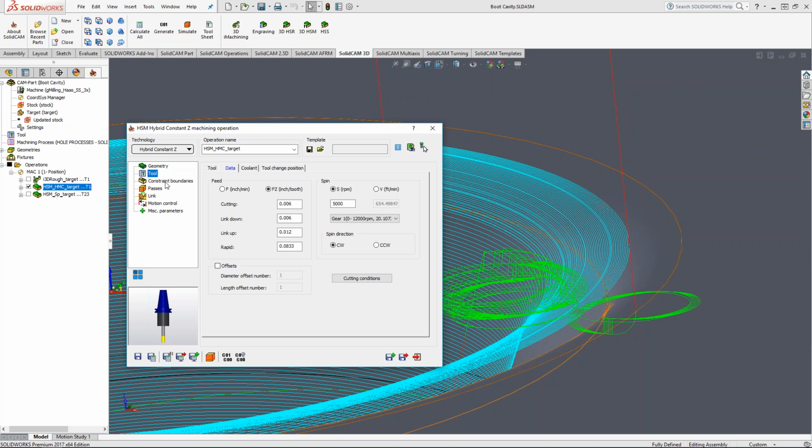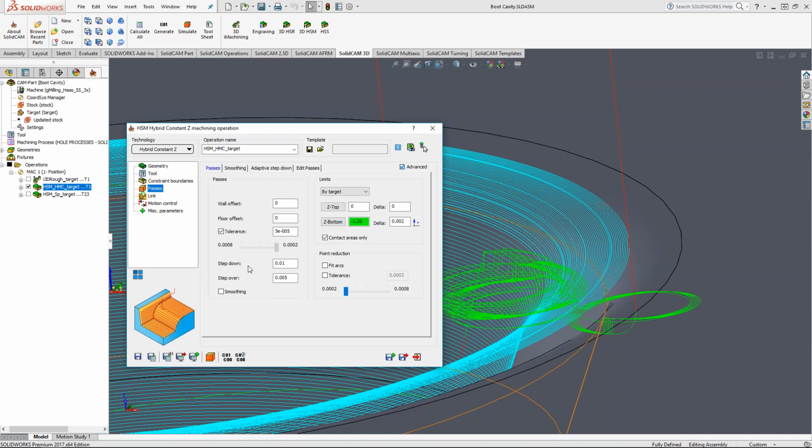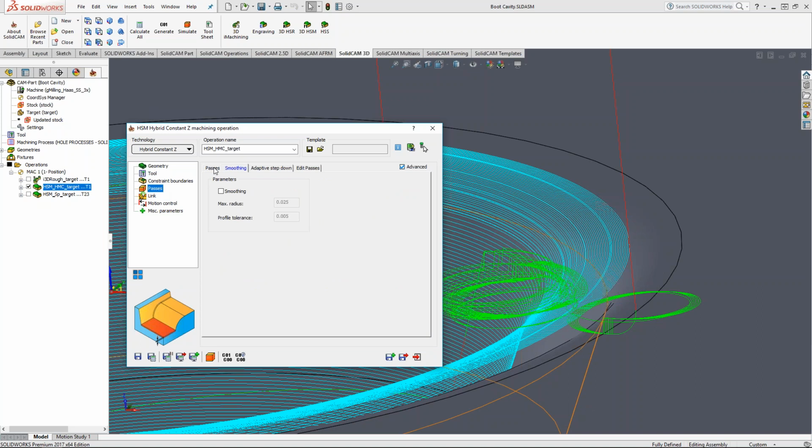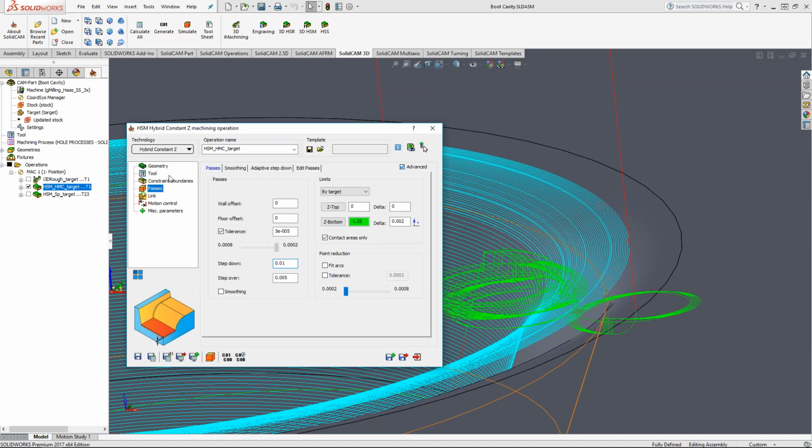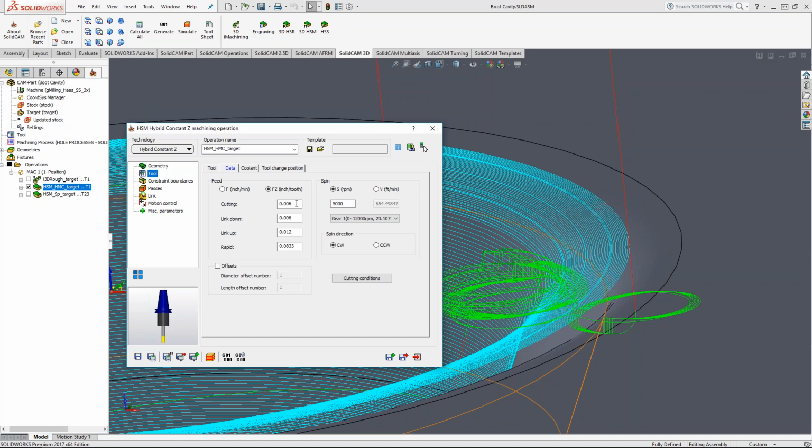So I think cutting this tool, the cusp height down these steps came out somewhere in the neighborhood of about 50 millionths, somewhere around in there. And this was a .010 step down. So I just translated that over to a .006, basically .006 step over per tooth. So that gave me a pretty smooth finish. Didn't have a whole lot of polishing to do there.